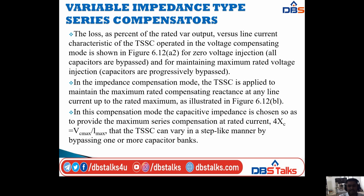In this compensation mode, the capacitor impedance is chosen so as to provide the maximum series compensation at rated current, that is XC equals VC maximum by I maximum. That means the TSSC can vary in a step-like manner by bypassing one or more capacitor banks.